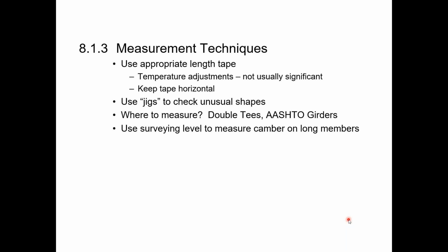I've seen plants use robotic total station surveying equipment and a small little prism that's designed to be placed in very specific parts of that piece, and they'll take multiple shots with that surveying equipment, and then it plots a surface that can then be compared, to compare the actual to the required, and determine whether or not the tolerances are being met.